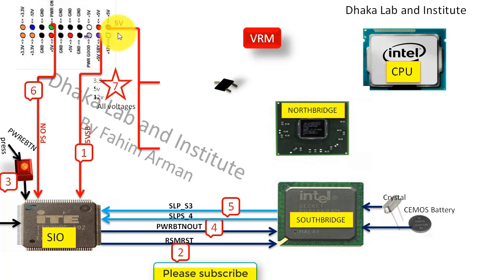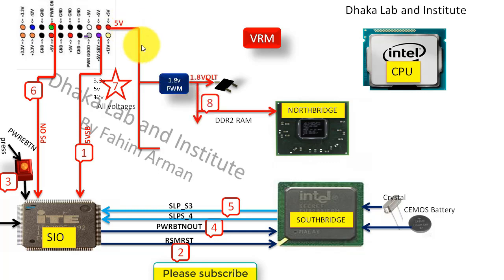First, 5V will pass from the 5V side wire and will first go to the RAM section, as it is a DDR2 RAM board. The RAM section will provide 1.8V, and then 5V will also enter this linear regulator, and that 5V will be converted into 1.25V and enter the North Bridge.